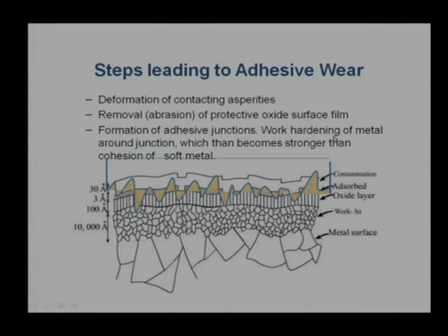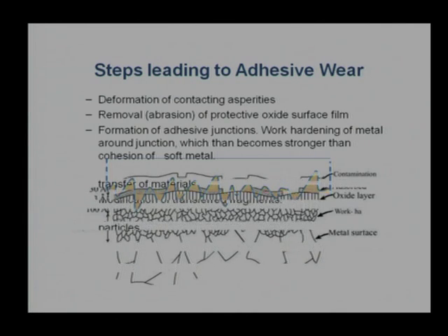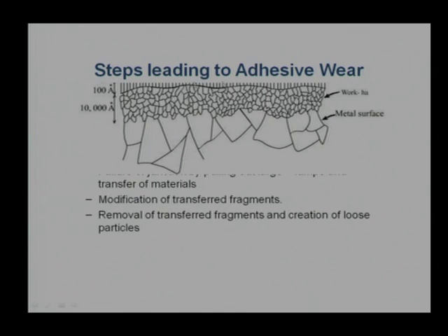However, there is a possibility of work hardening of the metal, which may increase strength, but if that layer is also removed, then there is more chance of wear. We can project it something like this. We say that most of the layers have been removed. Now, only the work hardened layer is remaining, and if this layer fractures or its properties change, bringing more brittleness, it removes the piece as it is from the surface.